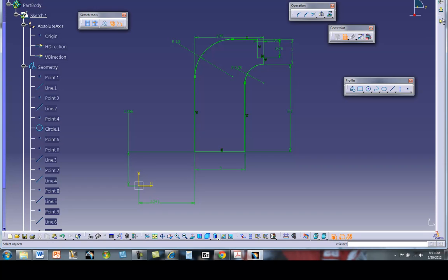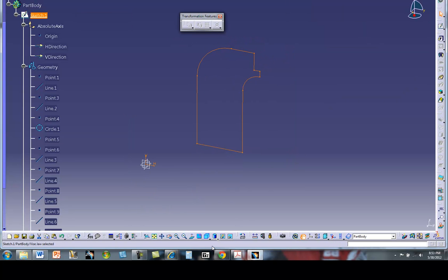So I'm going to exit out of this particular sketch here, go back in isometric view, and now we want to create a pad out of this feature. So coming over here, okay, I got the feature selected here. So its value then is 1.5. Let's see here. Select the limit, use a formula to set the second limit. So again, let's go in the pad here.